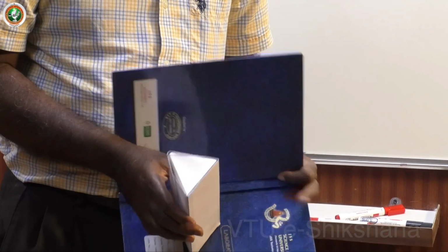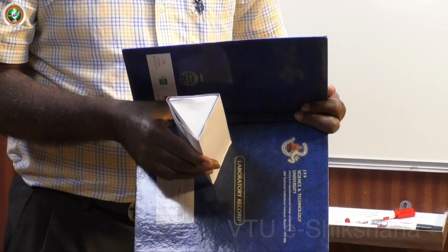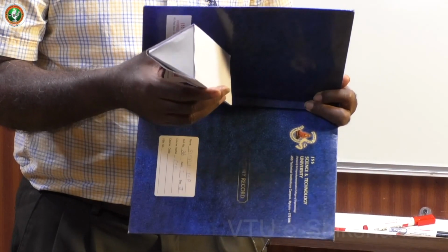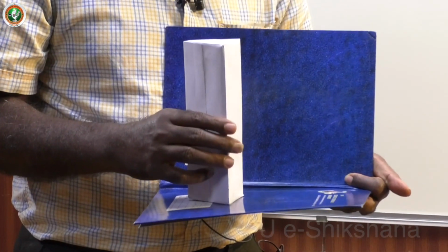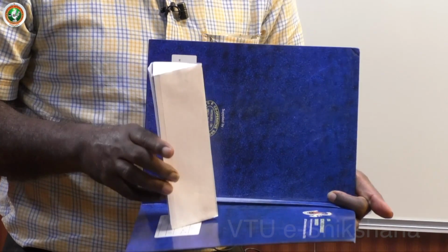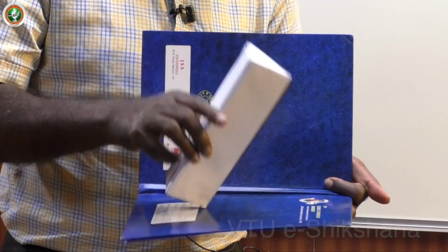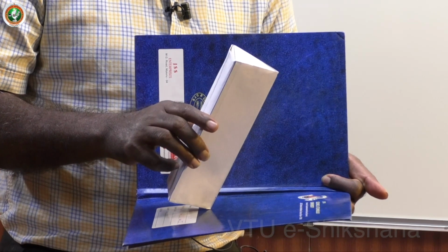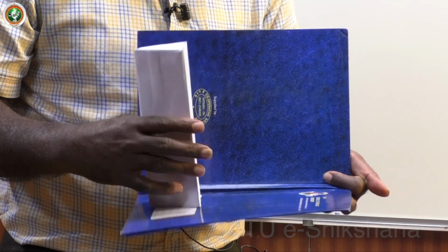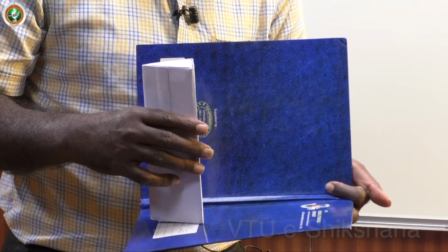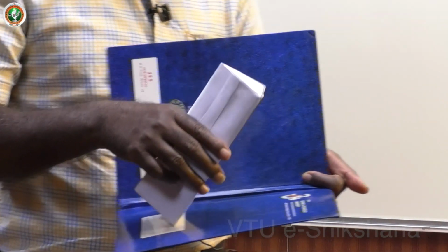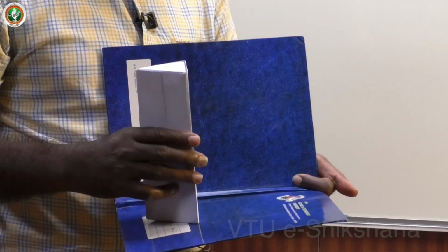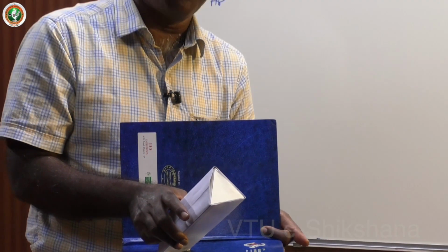Now I will tilt so that you can understand better. See, you will get the true shape. Assume that this is HP, this is VP. If you do like this, then only you will get the true shape. So first position, second position. Let me try this. First position, try second position. So the corner on HP, we don't want. So base edge on HP is inclined 45 degree to VP, and the axis itself is inclined 30 degree to HP. First position, second position, third position. So this is what the problem is given.